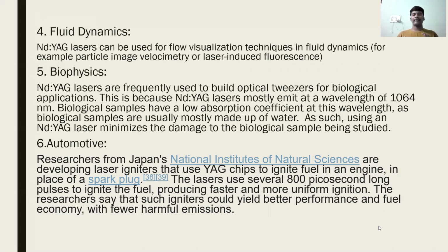Every engine in any vehicle starts with a small spark, but instead of using a spark plug, this Japanese institute is trying to create a new technology of starting an engine using YAG chips, which emit a particular wavelength through which we can produce a spark. The lasers use several 800 picosecond long pulses to ignite the fuel.